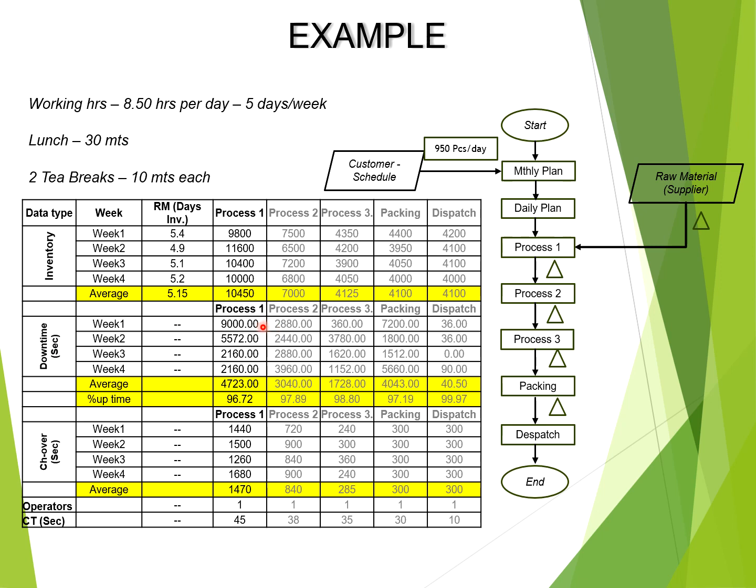The downtime, weekly downtime is noted, and then we take the average. To find out the uptime, this was 8 into 5, 40 hours. That means 1,44,000 seconds. So in 1,44,000 seconds, we reduce the downtime, 4723. Then 1,44,000 minus 4723 divided by 1,44,000 shall be the uptime.